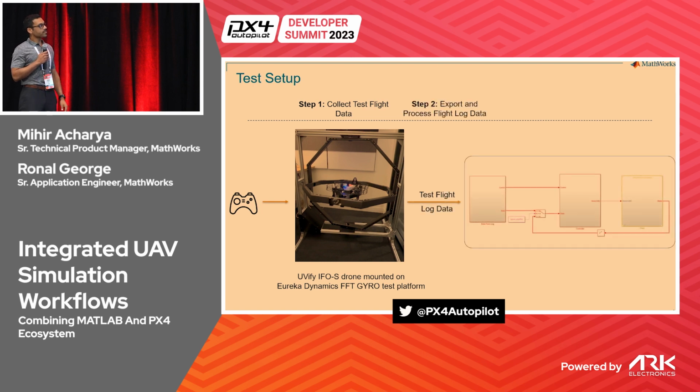The next step was putting this through our Simulink model. There are 3 pieces here. You can see there's one that just reads from the log data, one that says controller, and one that says plant. First step, keep it in open loop. Read from log data, send that data to your controller, and validate that the simulated controller, as in your actuator controls, comes out the same as your log data. Your parameters can come directly from the log file too. If you've seen PX4 logs, you get all your parameters. So validate the controller, make sure it's the same.